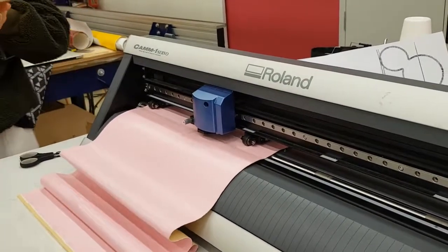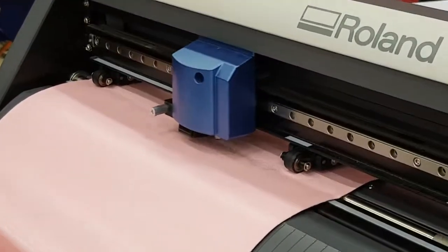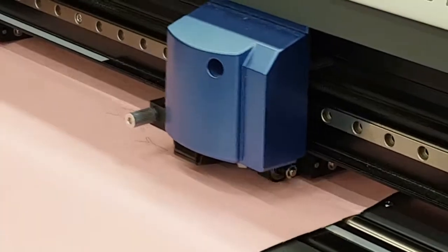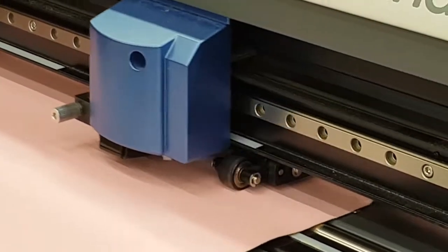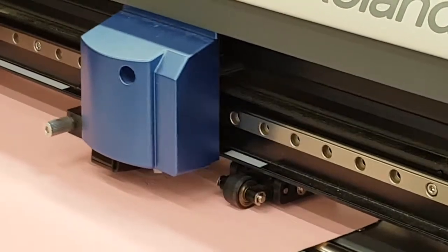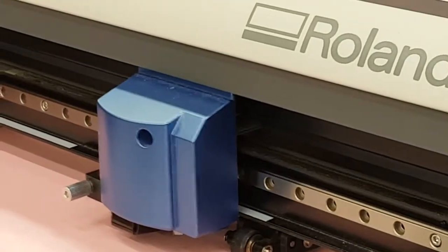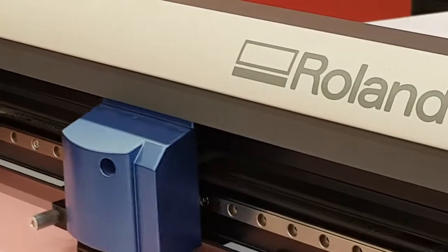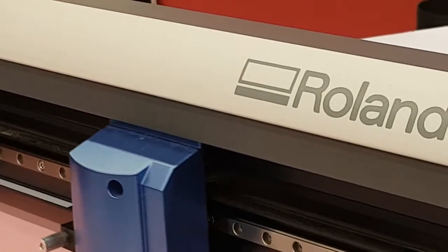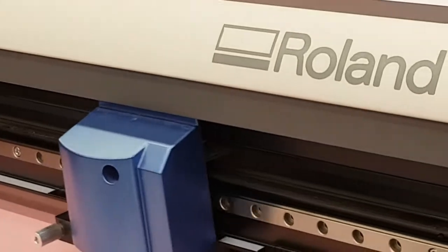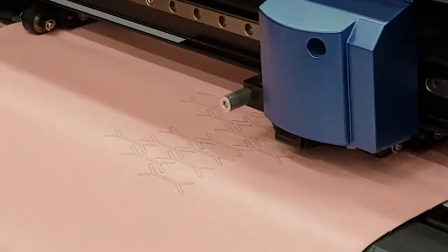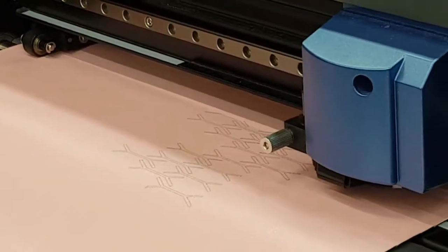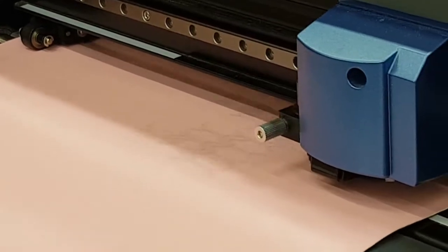Possibly we want a little bit more pressure, or maybe a slightly different type of pen. Maybe the felt is amazing. Still some stuff. There is also a slider here where you can adjust the pen force midway through the cut. Not in any kind of significant amount, but sometimes it's enough to make a little bit of a difference. If you do that, make sure to put it back to 0 so the next person isn't surprised by an unexpected force adjustment.